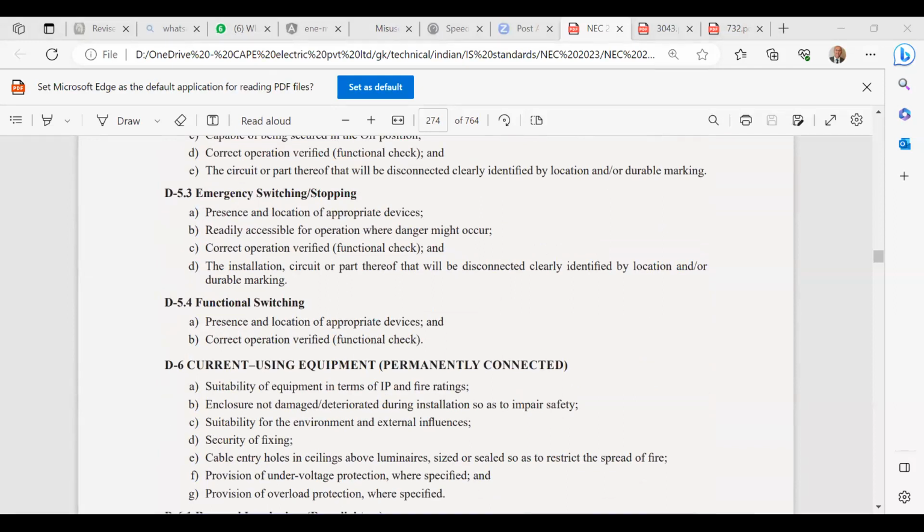What exactly we are talking about in this particular subject is, basically, every electrical network has a maximum disconnection time. The first job is, in case of any fault, before people get a shock, the supply has to be disconnected. So the full name of the safety measure is protective equipotential bonding and automatic disconnection of supply.